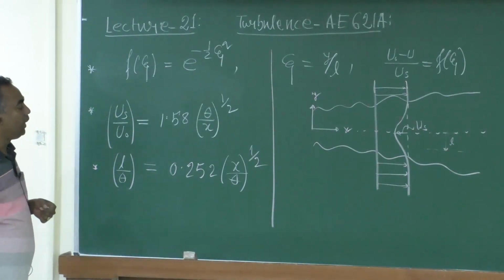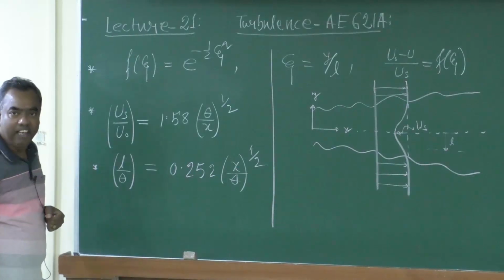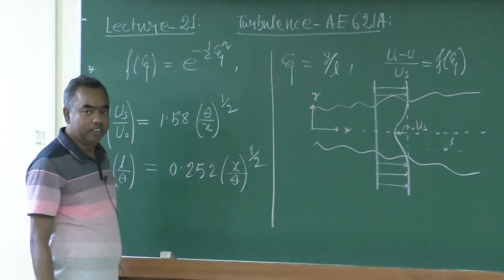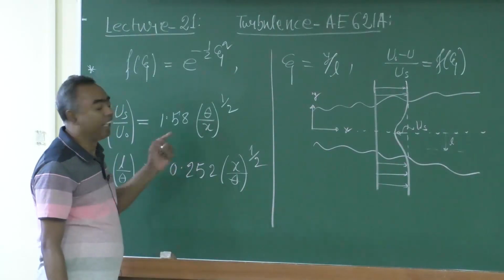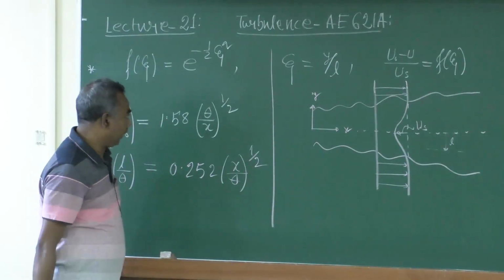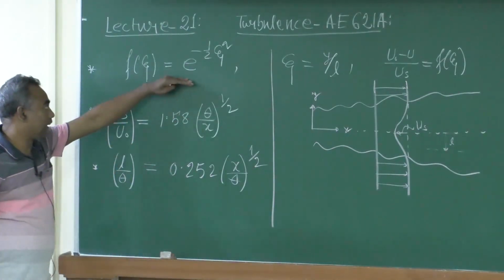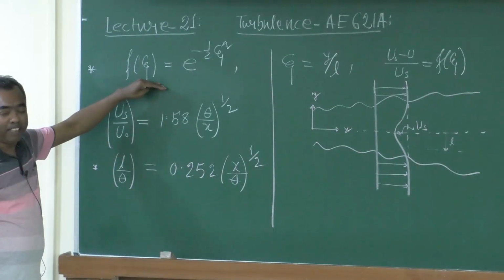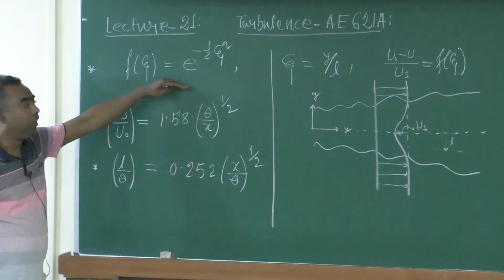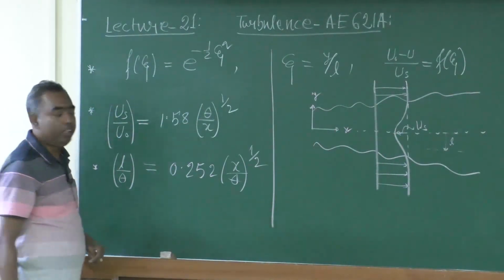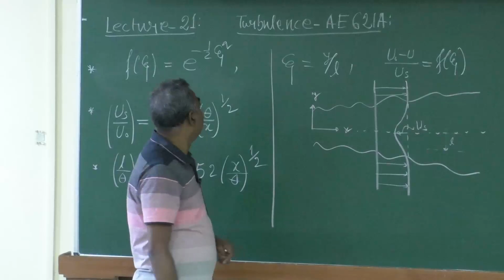So, today mainly we are going to consider some of the scale relations and the turbulent kinetic energy equation, or its simplification, for these particular solutions for a turbulent wake. And I mentioned in the last class that this particular profile is seen to match very well near the center line of the wake. It only slightly deviates, about 5%, towards the outer edge of the turbulent wake. Okay. That is what we talked about in the last class.